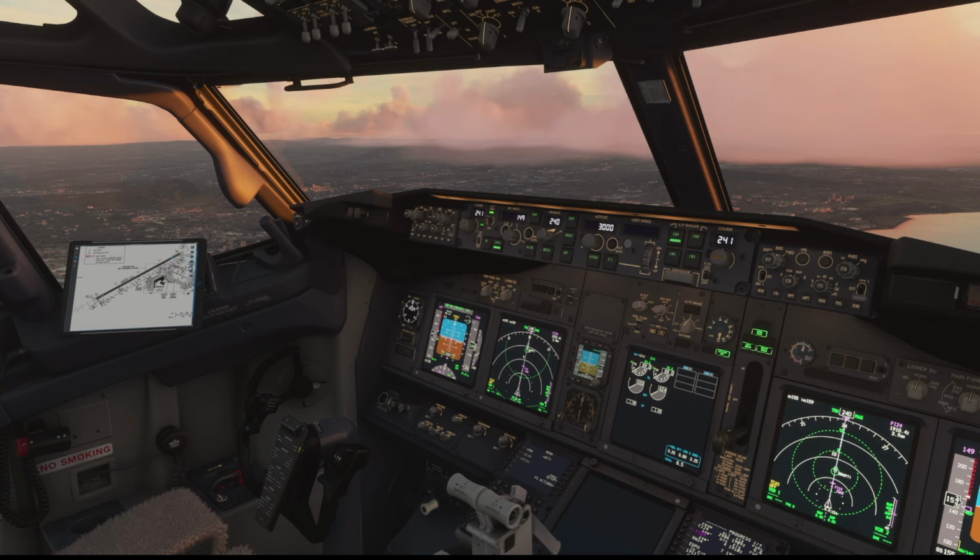Firstly I'll show you how to activate the HUD. So we go into Setup and then Aircraft, and then we go to Equipment, and we need to scroll back to page 12 of 17, and then we'll see the HGS installed option, and we hit yes, and that gives us another couple of options which we can also activate for the heads-up display, but I'll leave those off for now.